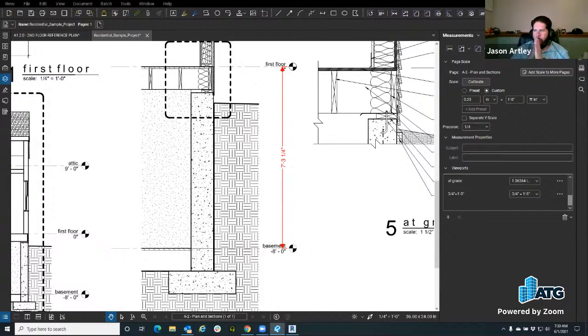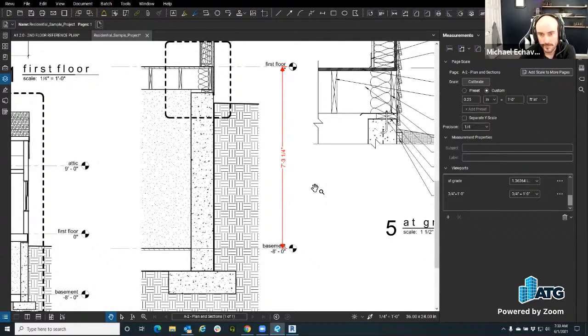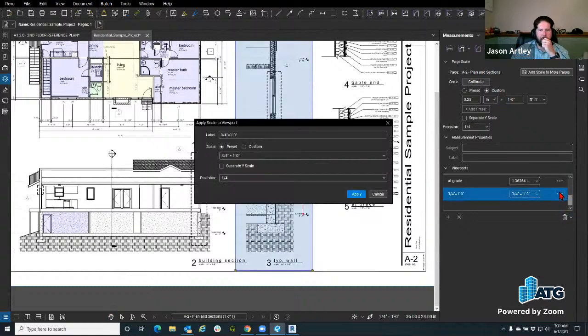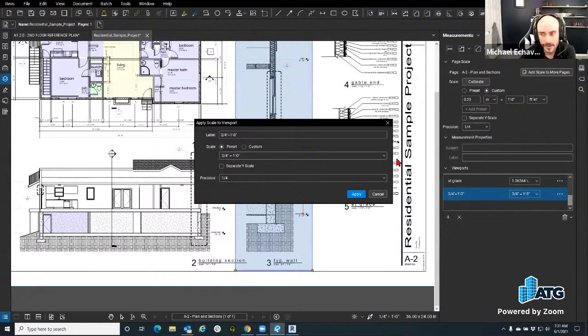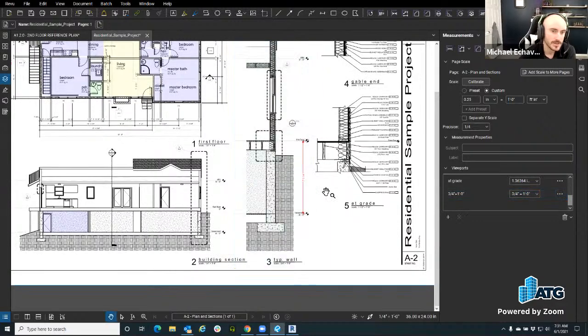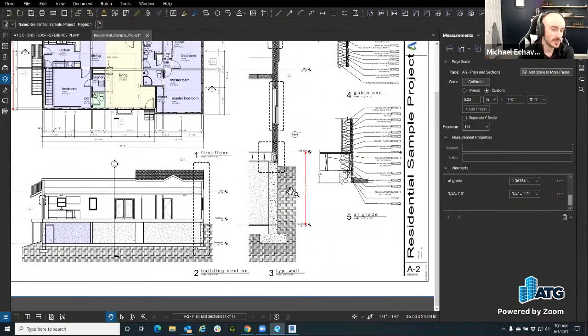Ooh, there's a good question from Mindy. What other uses do viewports have? What else can we do with them? So if you click on that 3-dot ellipsis over there, that just brings you to the scale. So it's the same thing that comes down to uses for measurements, right? Different scalable markups. So if you're trying to transition from one scale to the next on the same PDF, that also is like a punch walkthrough, right? A punch list. If those markups are set to scale, they would change and transition specific to the viewports that you have on the sheet set.